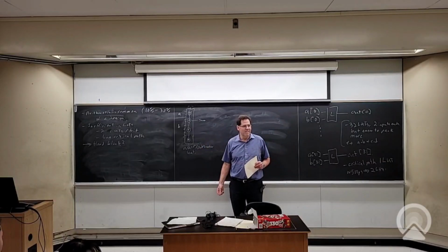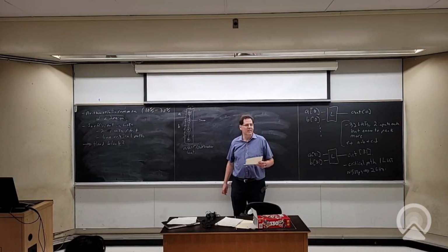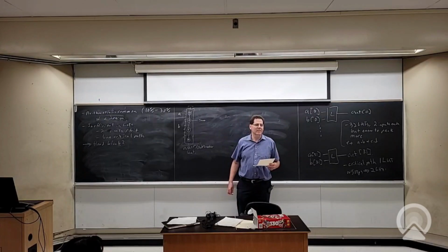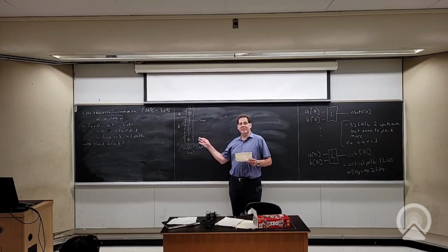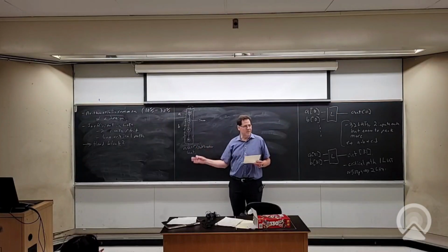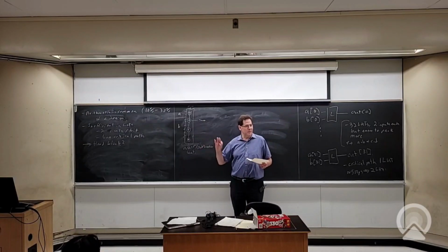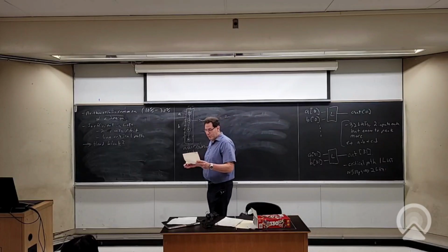So if you're going to make it its own tile, you're saying these adders are really tiny, so tiny in fact that you want to match the size of the CLBs, which means you're going to need to put a bunch of adders in there, which is going to require a ton of inputs. Okay, so you think this is going to be a pain to lay out because I put in a tile of this and a tile of CLBs. This is too small. And I guess tiles do get routing channels and stuff. So yeah, you're right, it is going to be a pain.